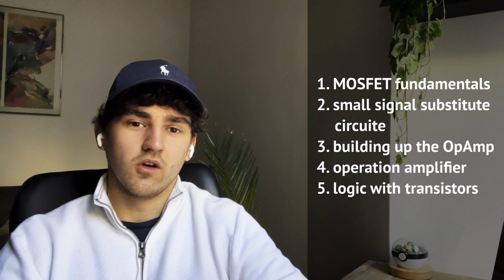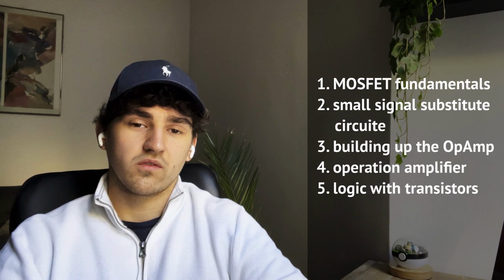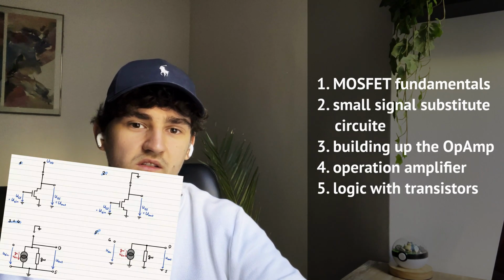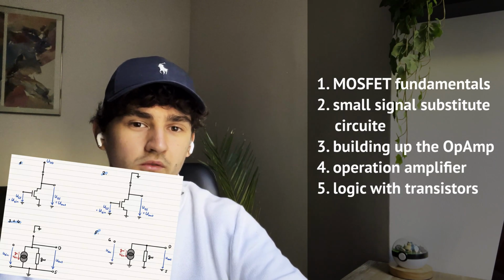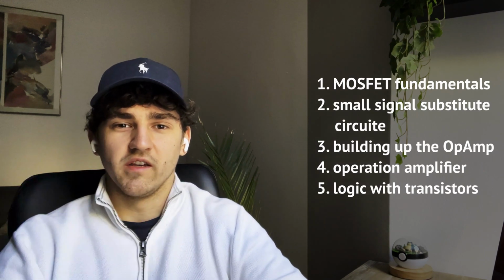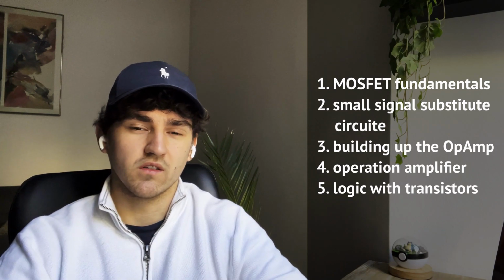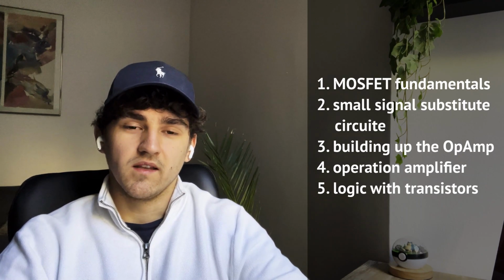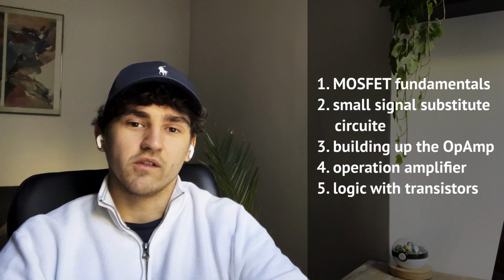For that reason, you will learn an approximation algorithm to break down or transform a MOSFET circuit into a small signal substitute circuit. Small signal because you have the assumption that your input voltage, the gate voltage, will not change that much. And with that you can basically again calculate the transfer function, or in this case it's rather considered the amplification. Later on you will obviously also take a look at the big signals and what effect they have